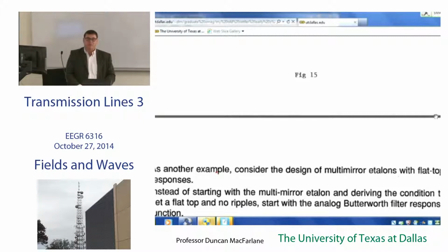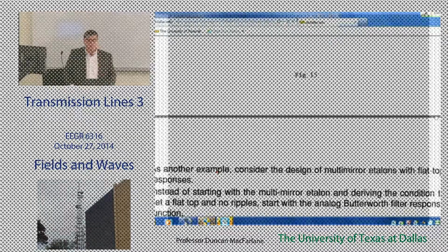So that's what I meant when I said, Smith charts are really nice, they're interesting. They're not hard to derive. They're fun to do problems, but there's a very limited class of problems with which you can solve. If you start to have too many of these links of transmission lines where the feedback is too structured, you'll go nuts spinning around and around and around your Smith chart. And by the way, that's only at one frequency. This approach is suited to MATLAB. You're already good at MATLAB. This is a much cleaner, nicer way to do those kinds of electromagnetic problems.